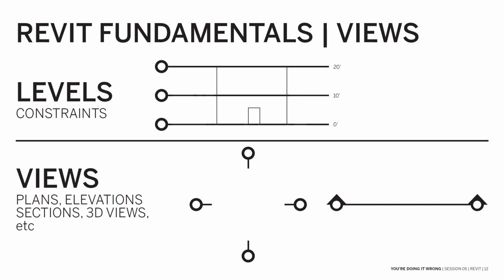Views. So what's amazing about Revit is that all of your views are synced because they're basically derived from the same model. So your plans, elevations, sections, and 3D views all automatically update when an element is moved or changed. So if I move a door in plan, that same door will be moved in elevation, in section, and in all your 3D views, etc., which is a massive time saver. So you don't have to remember to edit every single drawing. For example, if you're doing them all in AutoCAD, you don't have to remember to move that door in all of your drawings. Revit does that automatically.